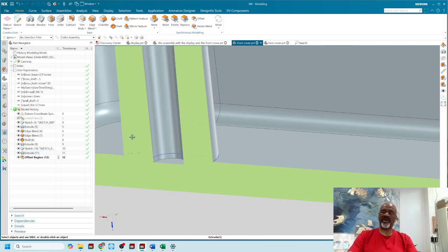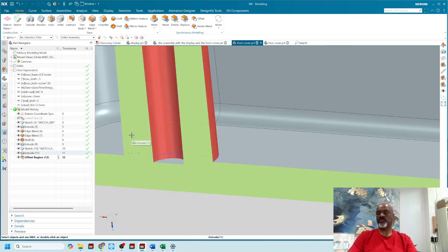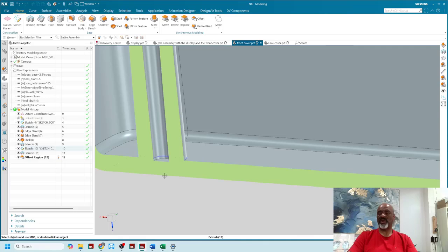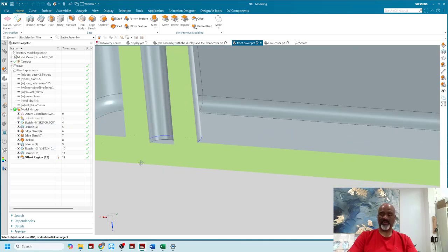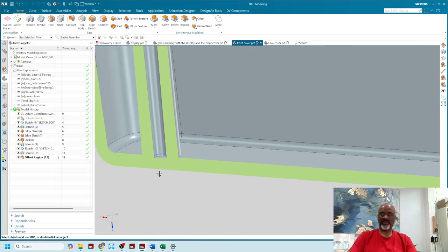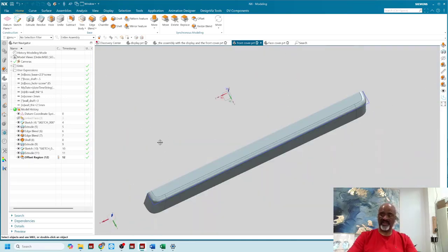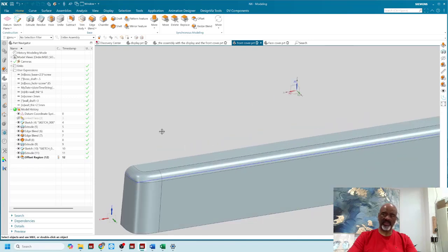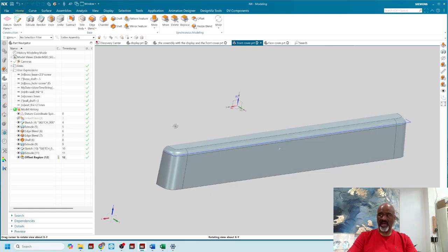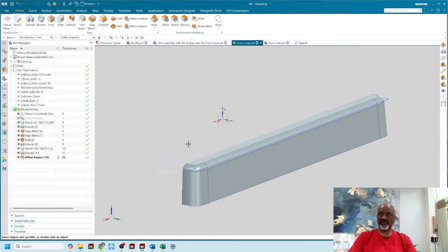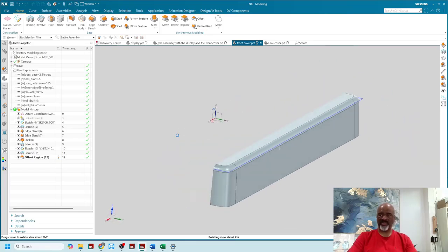So what I'm worried about is the shrink. What I'm worried about is when this thing sets up with the shrink of the material, that there'll be a little indentation there, and it'll show where the boss is, and that won't look good, especially on the front face. Incidentally, the A surfaces, an A surface, a lot of people think that A surfacing and B surfacing is a mathematical thing.